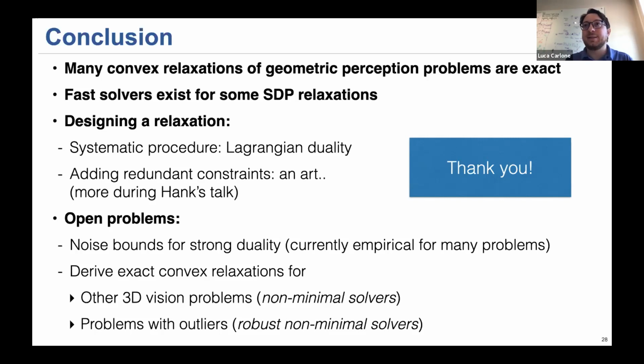Yet another answer is that you use a local solver most of the time, use GTSAM and these existing local solvers, and use this theory in the background to sanity check that the solution from the local solver is optimal, which is this idea of optimality certification.